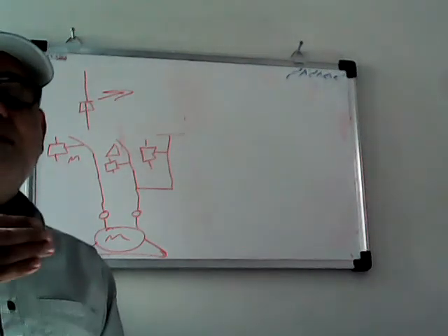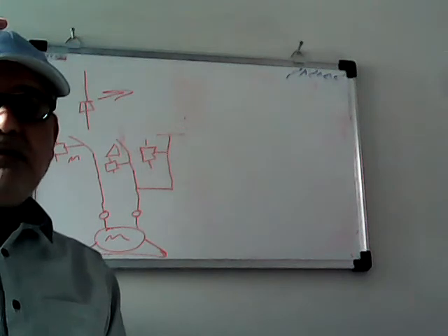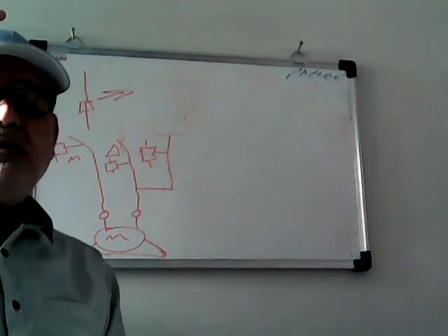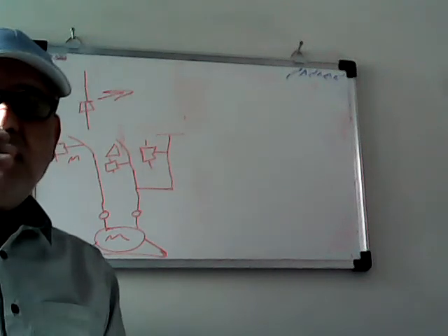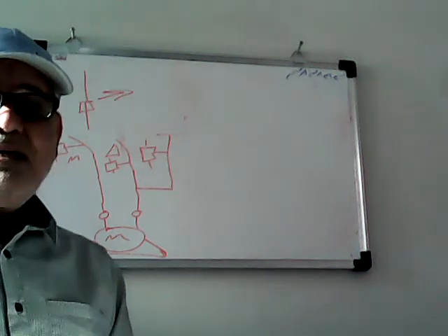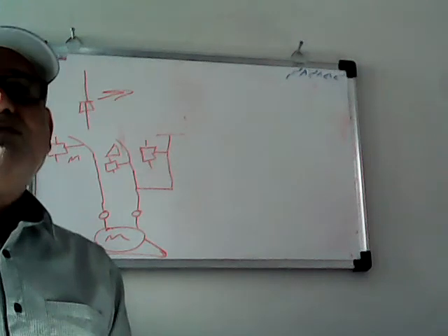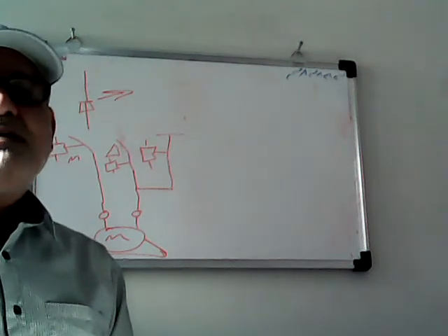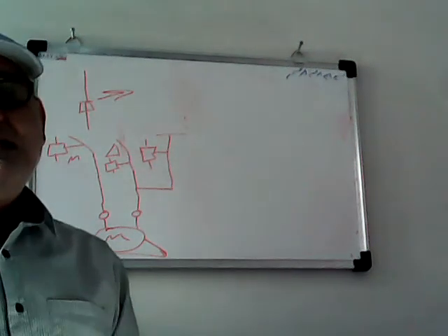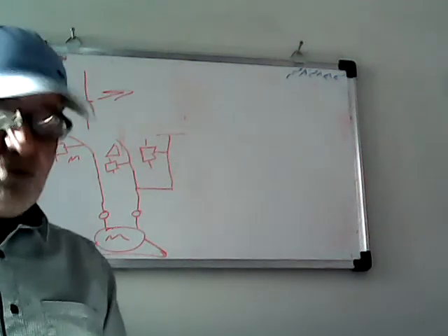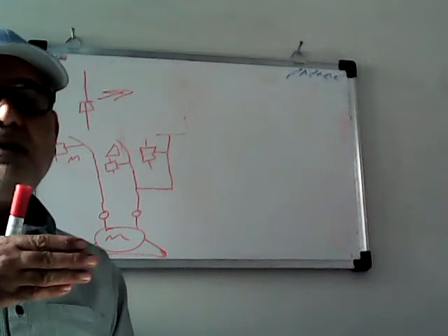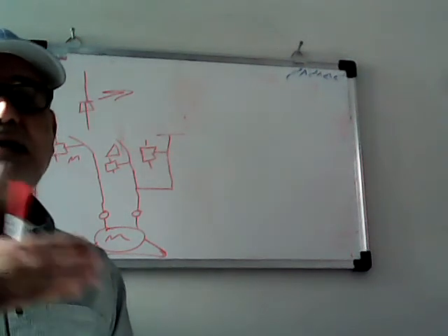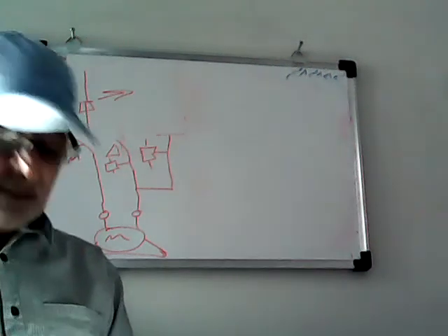When you divide the nameplate current of your electromotor by these numbers, you find your fuses easily and fast, as I described before for the other two running and starting methods, DOL and type 1 star delta.